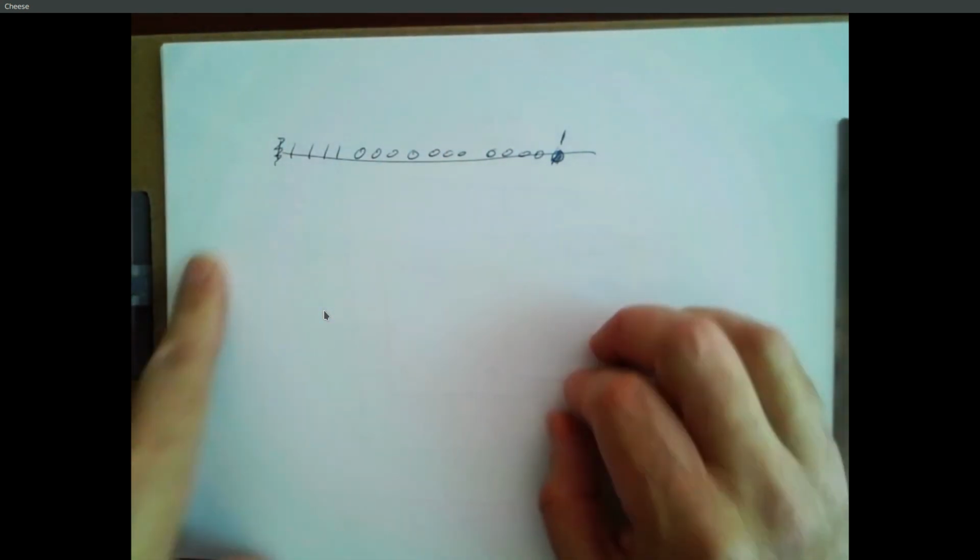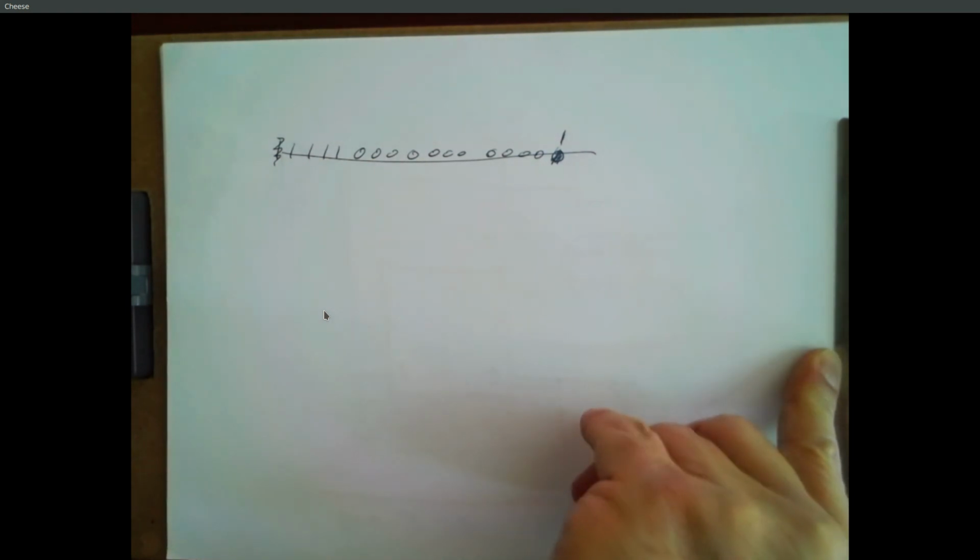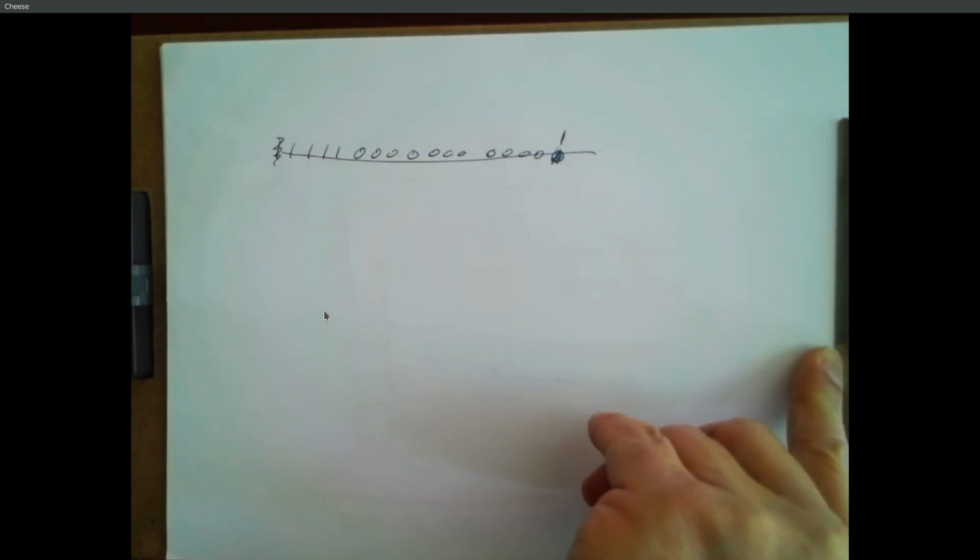So if you shift your events into a 16-bit shift register, all you have to do is count how many ones you have in that shift register, and if it's equal to 5, set your output to 1. Otherwise, set your output to 0. So it's a combination of the shift register from experiment 4, but 16 bits instead of 8, and then some combinational logic that basically counts the number of ones.